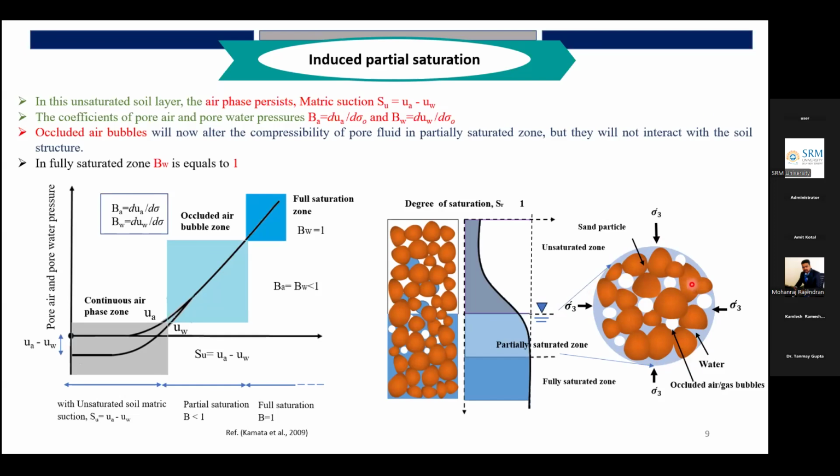So this is the simple mechanism. This mechanism is not a new one. It is an already established mechanism. But we want to create a system for how to make the calculated air bubbles keep the soil at a particular degree of saturation to maintain the liquefaction resistance of the soil. So this is the whole background of this particular study.